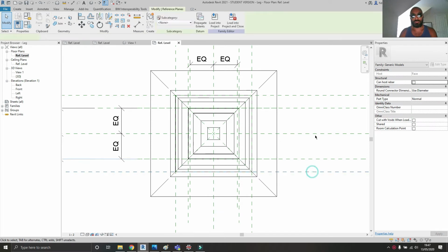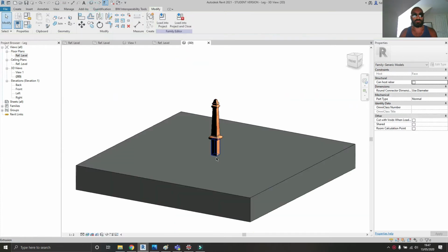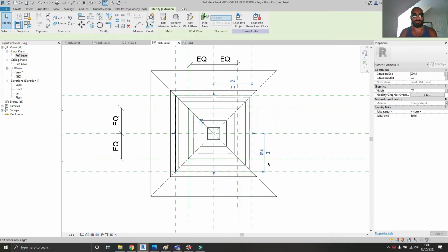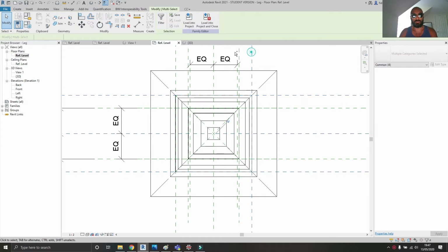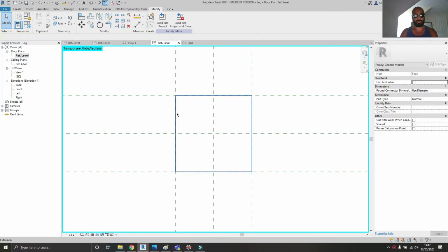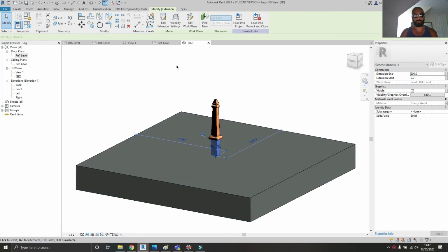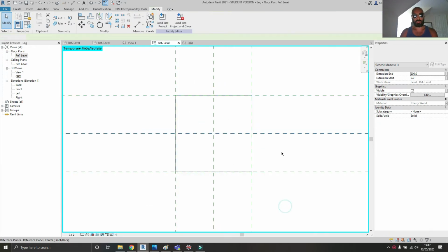So select this, this, this, that, that. Those are the outs. Oh no, sorry. Go to 3D mode first. Select this. Now, without clicking anything else, hold Control. Select this, this, and this. This, this, and this. Type HI for hide isolate, and we only have that piece that we highlighted in 3D mode. Yep, see. And the reference planes.